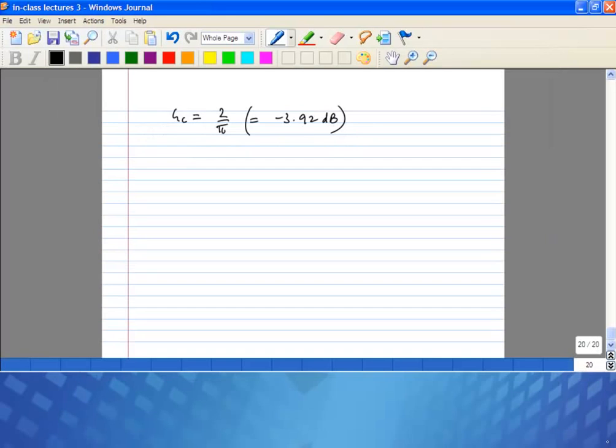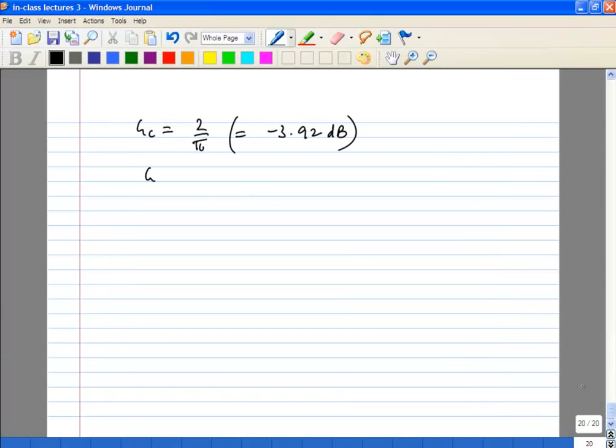Okay. But if you look at practical implementations, most of them have, let's say, 5 to 6 dB loss, I'll put it that way. Okay, because of other non-ideal effects. Here we have assumed it's a perfect switch. In other cases you can have losses in other places, so it will end up being slightly lower, another 1 or 2 dB lower. Okay. The other thing is you can show, I'm not going to show it in class, but you can show that